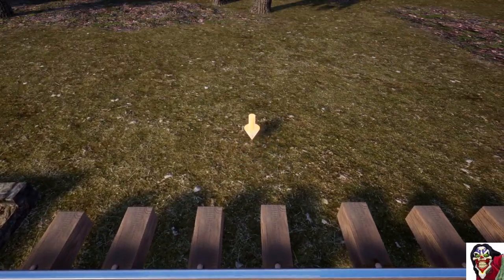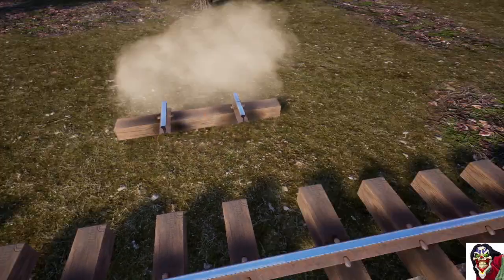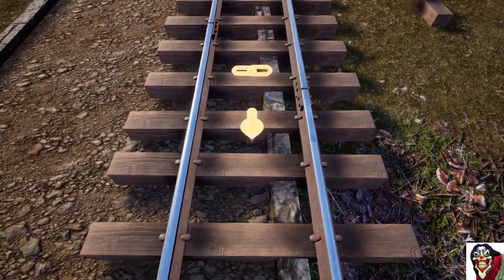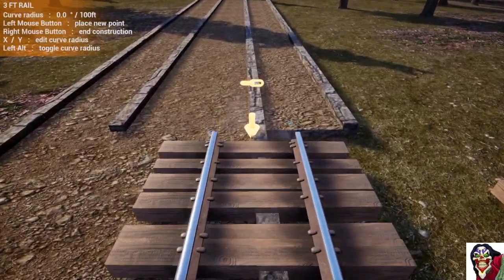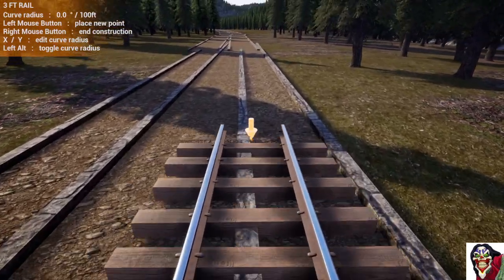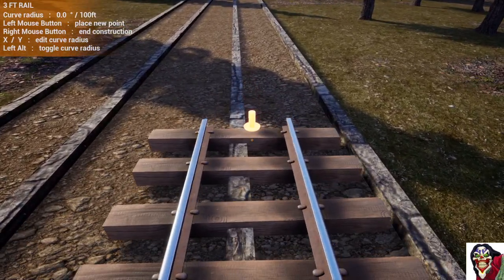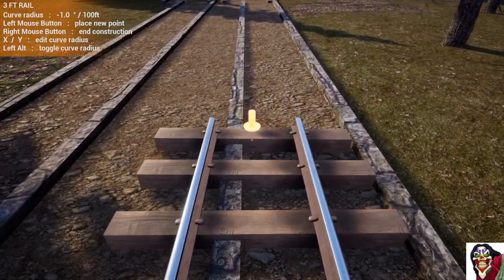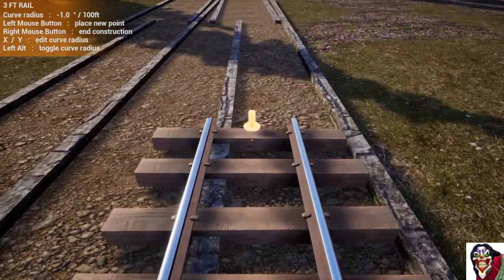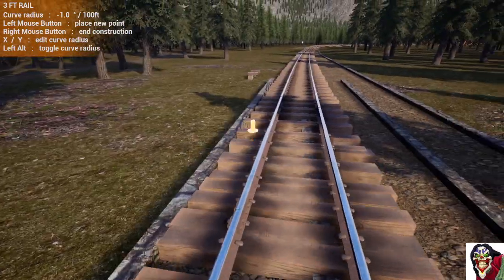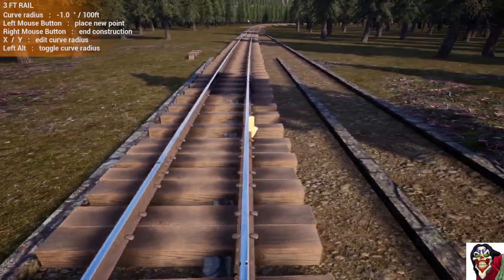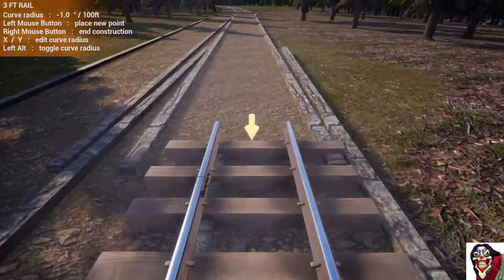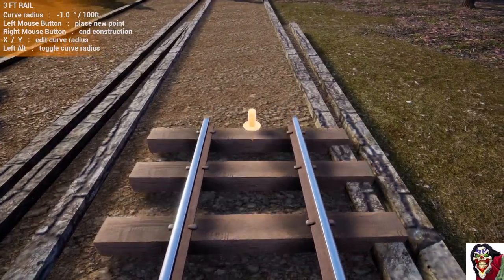Now it's a good idea to mark the spot where you've got the overlap track because sometimes it's hard to see where the overlaps are. It makes it a little bit easier to come back and remove them later. And then we'll put in our 1%, continue to build. And you can see there that there's no wobbles in the track where we've had to resume building.